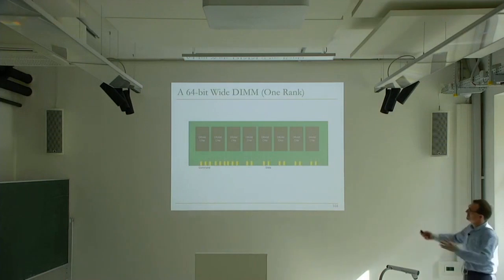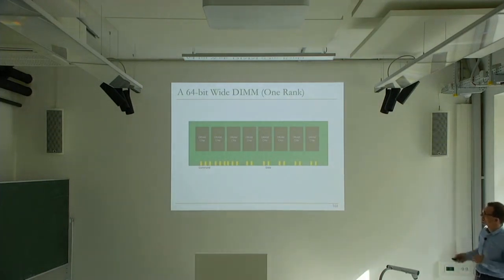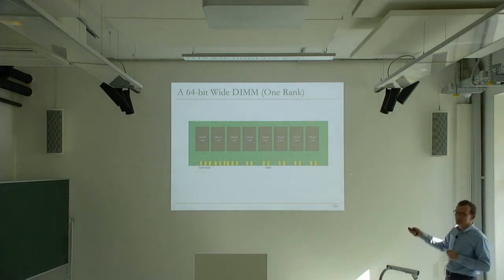So clearly, a DIMM is nice over here. The reason it's done this way is this keeps the chip cost low, because you don't need to add more pins. You just need to add another module that has this sort of interface. And these are cheaper than the pins.